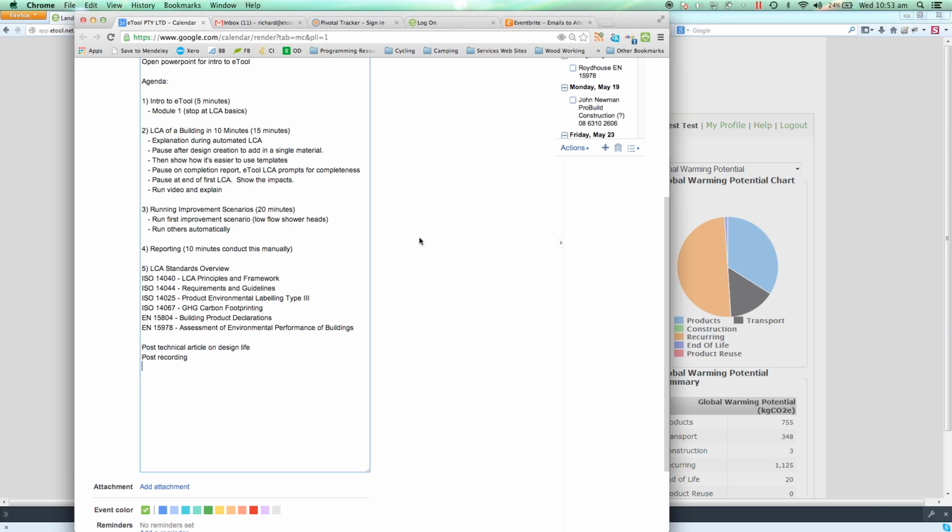You definitely run with the steel because you can feed that back into the economy, if it was just an environmental decision. Whereas concrete becomes road base, it's effectively a waste material that gets downcycled at the end of the building life, whereas steel's actually got value at the end of the building life to be used in another building, either fully recycled at a steel plant or even directly reused in some cases as well.